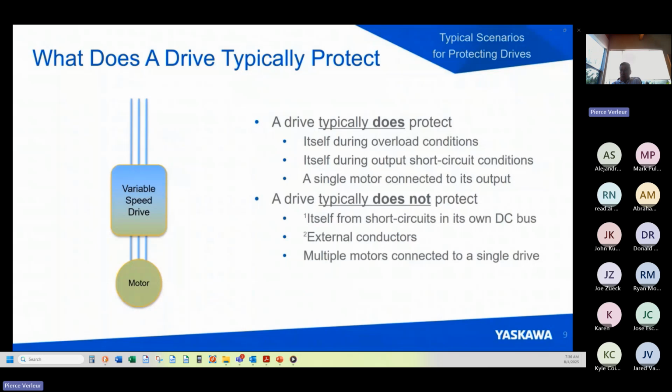But what does a drive typically not protect? It typically does not protect itself from short circuits in its own DC bus. It also typically does not protect external conductors or multiple motors connected to a single drive. There are a few exceptions to that, because there are some specialty and large drives that include short circuit protection for the DC bus, in other words, built-in fuses. An example of this would be the Yaskawa U1000 Matrix product.